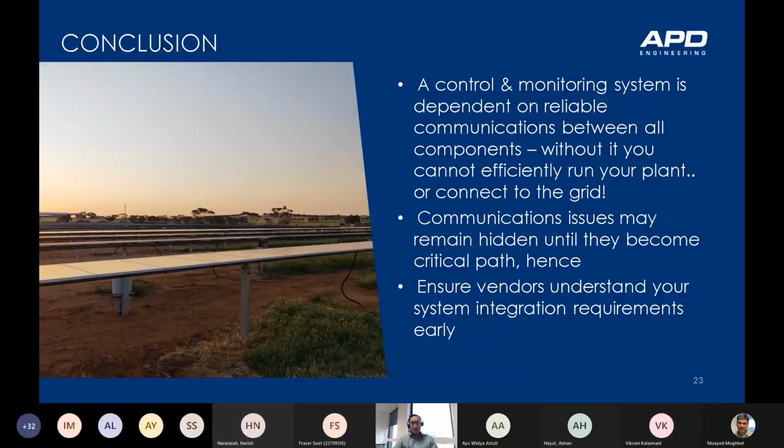But did you have access to the equipment? We didn't have access to the equipment. Eventually, we had to do some trial and error, as you mentioned, separating some of the high demand devices like PQM meters onto a separate network. Any packet loss from that PQM, like the connector grid and disconnector grid, just happens because of the comms loss, so it used to trip straight away. So we identified the issue, and then eventually we had to separate that network. And then everything was okay after that.